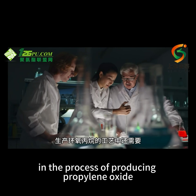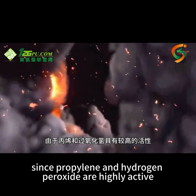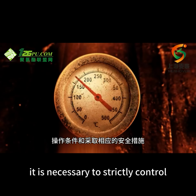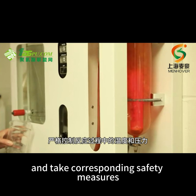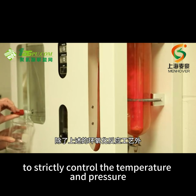a pure product. In the process of producing propylene oxide, another important factor to consider is safety. Since propylene and hydrogen peroxide are highly active, they are prone to explosion and combustion. Therefore, in production, it is necessary to strictly control the operating conditions and take corresponding safety measures. For example, explosion-proof equipment is installed on the reaction equipment to strictly control the temperature and pressure during the reaction.